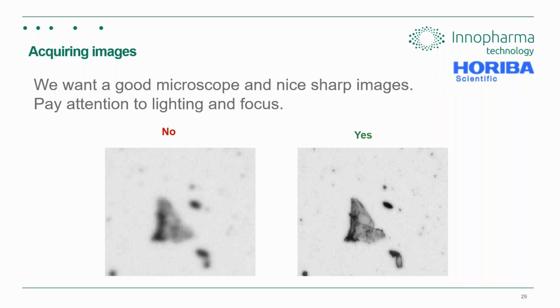So I guess the old phrase is, garbage in, garbage out. You have to start with good images. So it really is about the hardware setup at first, getting the correct illumination and focus for your material. And then from there, at least your image analysis, your processing, is all editable and configurable.